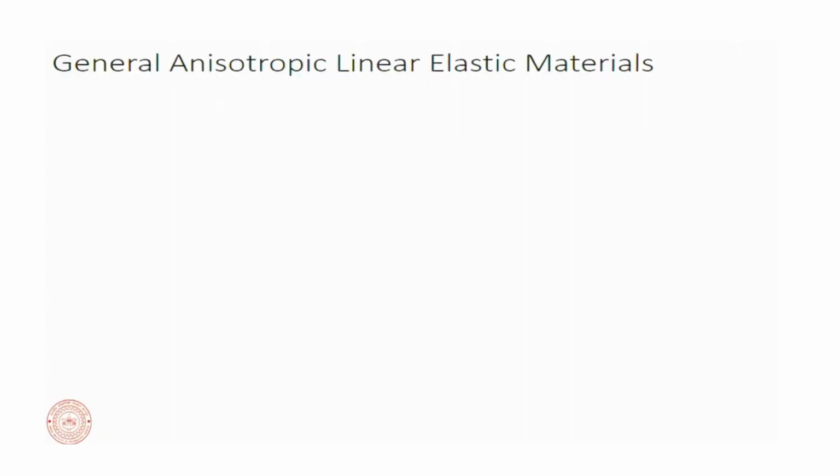So, we had gone all the way up to understanding these for a plane stress and plane strain in 2 dimension. Our models were dependent upon something that we were calling an isotropic linear elastic material. Isotropic meant that it was uniform in all directions. It was linear, that means that the stress strain relation is linear. It is elastic, means that it is able to come back to its undeformed state on the relaxation of the stress. Okay. Now we will go on to some brief definitions on a general anisotropic linear elastic material.